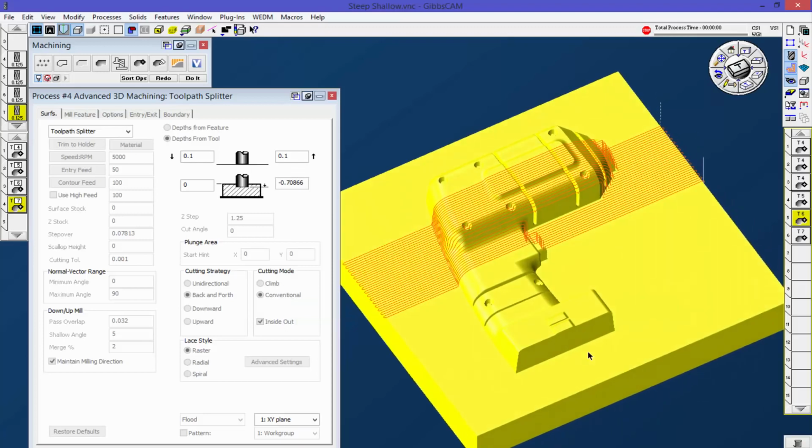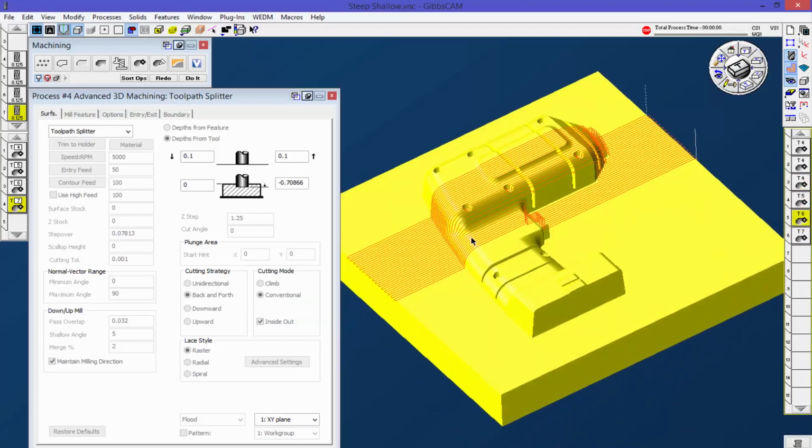So if it was really important for me to have sharp tools throughout this whole finishing process, this is a really great way to do it. What I've done in the past is, okay, I have to change the tool, so I hit pause on the machine, if your machine is able to pause in the middle of the tool path, take it out, replace it, change the offset in the controller, and put it back in. It's time consuming. This way you can put in 4 tools, have all of your offset heights set inside your machine, hit go, and it'll just do it. Lights out machining, you don't have to worry about changing the tool. This is a really helpful thing when it comes to finishing molds.